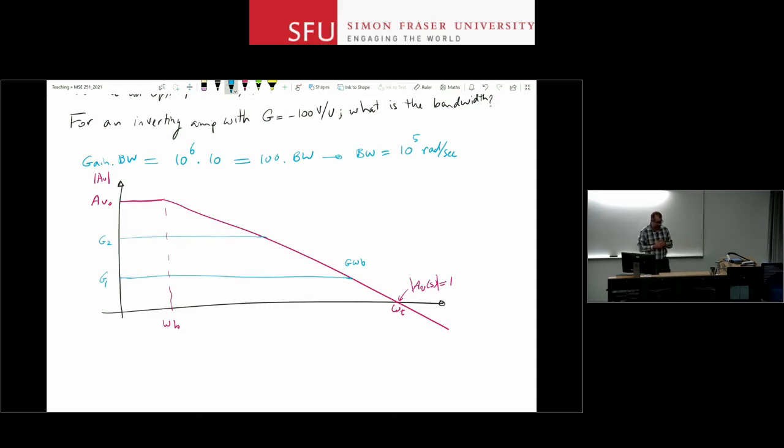You have to use a combination of op-amps, or maybe multiple op-amps in series with each other. But this issue of gain bandwidth products, just keep that in mind. Gain times bandwidth is constant. So gain of 1, omega t, a maximum gain AV naught, you get omega b, and then anything in between will be basically following the same principle.